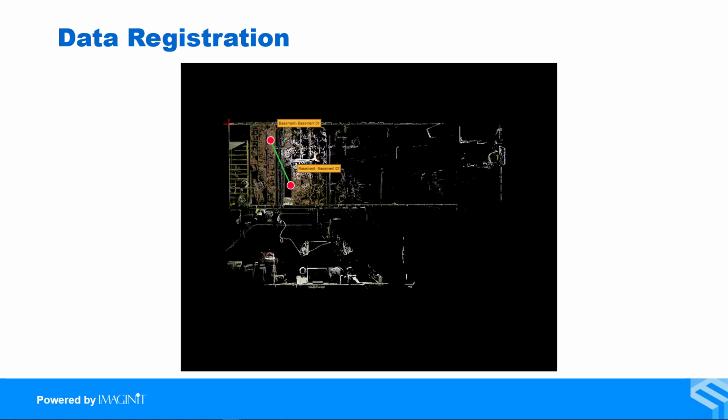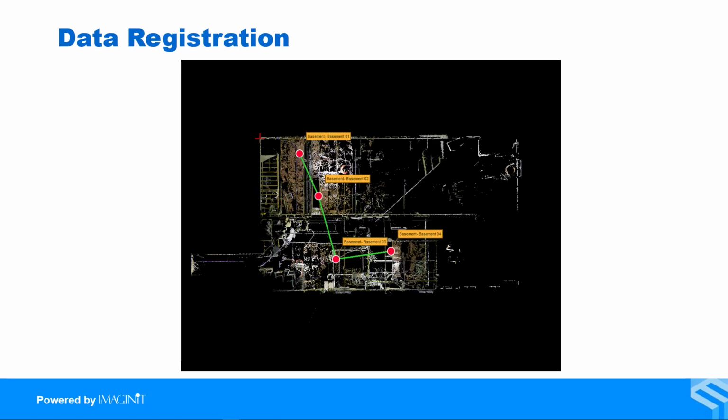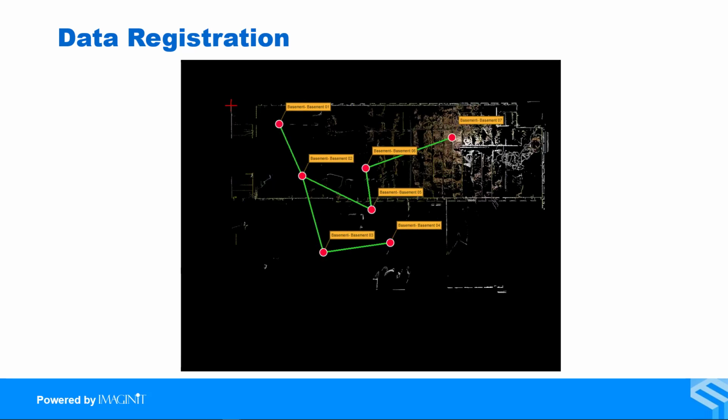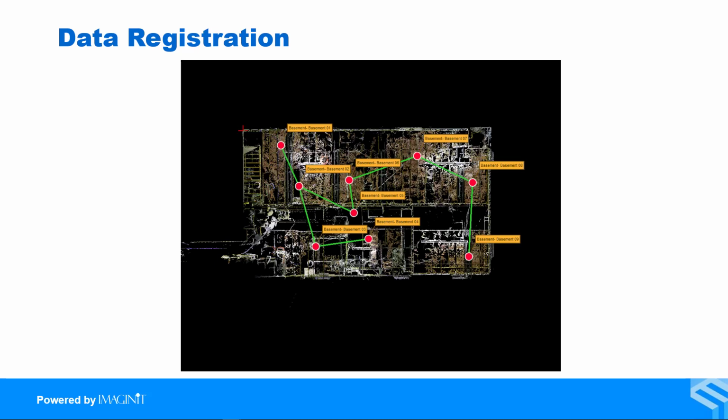After creating several individual scans, the data needs to be stitched together or registered. As we collect scans, they register to another scan until the project is completed. Once completed, the data can be cleaned up if you desire, but if we are using one of the scanners I mentioned earlier, we often don't need to spend a lot of time doing that to do a floor analysis.